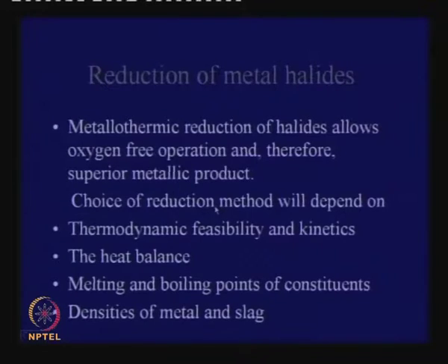But the choice of metallothermic reduction depends on a number of factors. First of all, the feasibility in terms of free energy change in the reaction, and in terms of enthalpy change, so that we can tell whether the reaction itself is making available sufficient heat. If not, we have to have a booster reaction, another reaction that supplies heat.